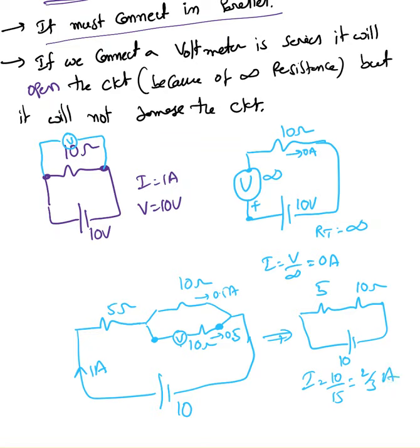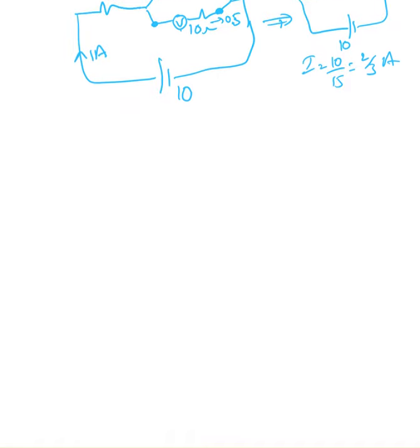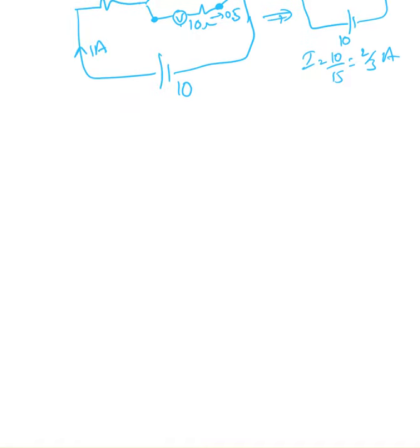So never connect a voltmeter in series, and never connect an ammeter in parallel. That's about the ammeter and voltmeter. Now I'm going to talk about two more laws, which are KVL and KCL.